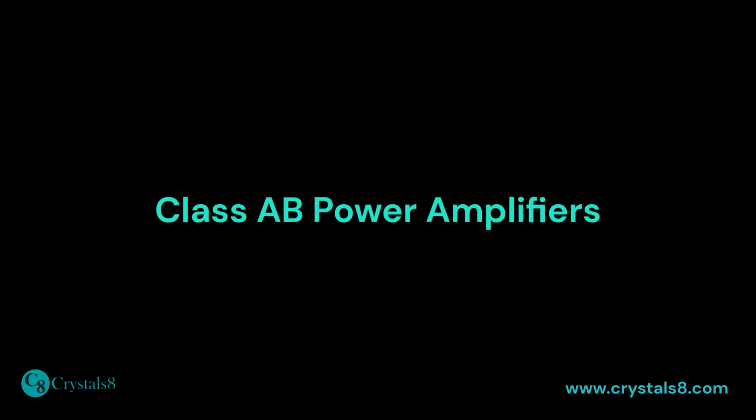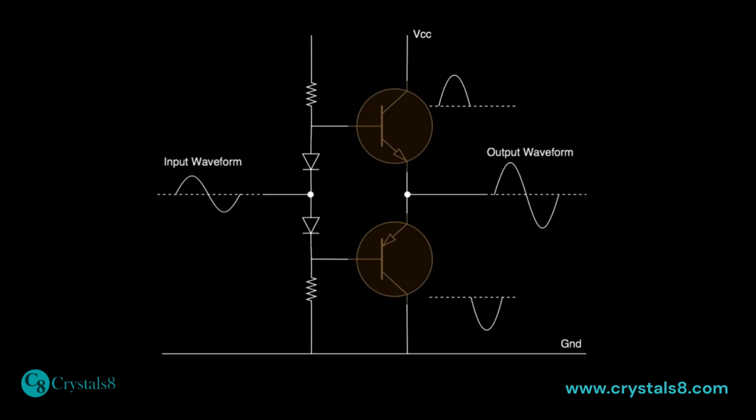Class AB power amplifier. This class of amplifiers was developed to overcome the problems of efficiency in Class A amplifiers and deadband in Class B amplifiers. The circuit is mostly equal to the Class B amplifier, and another two resistors were used to provide the required base emitter voltages of the transistors which are amplifying the signal. Due to that, transistors are sensitive to even a small change in input signal. The deadband problem can be eliminated through this.